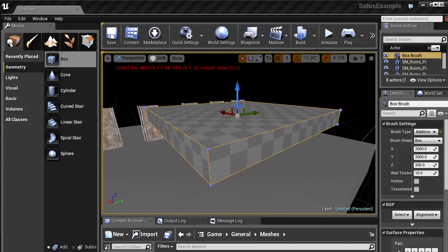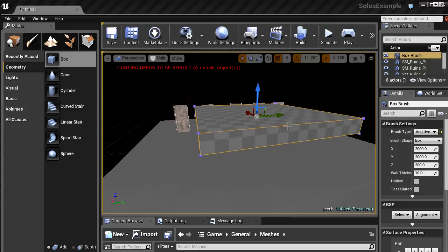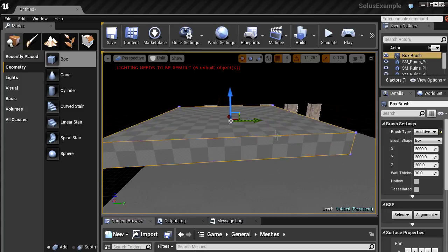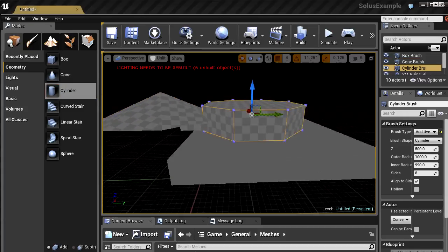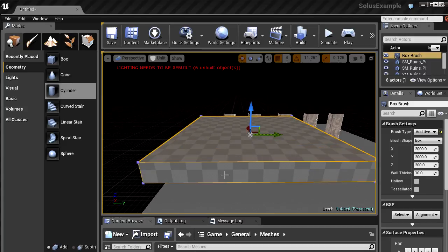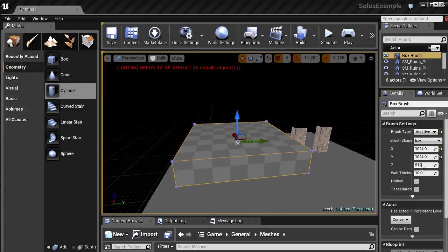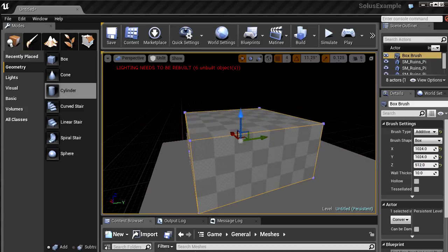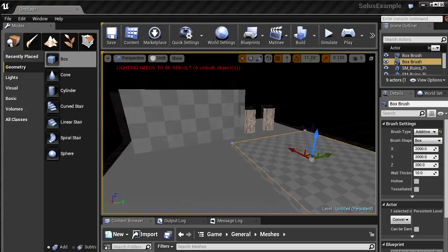Those of you who have experience with previous generations of the Unreal Engine, you can see you don't have to rebuild anymore. So it automatically updates the scene now every time you do something. That's nice. You can see you can drag in a cone if I want to, and a cylinder, etc. You can change the dimensions of these in the properties on the right side. Let me focus on the box to begin with. So I deleted those. If you want a different size, you simply type the size where you want to have it. So there is no builder brush anymore. For those of you who know the older generation of the Unreal Engine, there is no builder brush anymore. You directly drag it where you want to have it and change the type here, which is much faster than the old method.